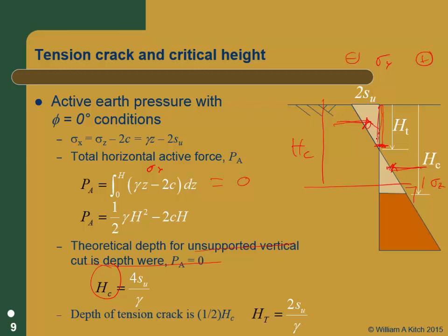And we generally like to, in walls, assume that the soil isn't actually going to suck the wall back and hold it up. So in those places where we get negative stresses, we will generally consider there to be 0 stress there instead of a negative stress.